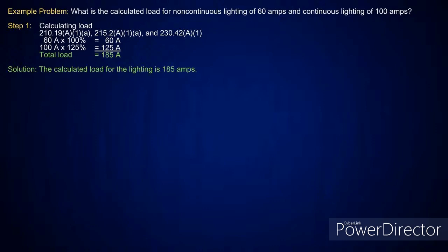Okay. Because I know they do the continuous load based on the breaker only being tested in open air, and then once you put it in that enclosure, you have to add that 25% for the heat dissipation. For the newbies, he's talking about the 80%.